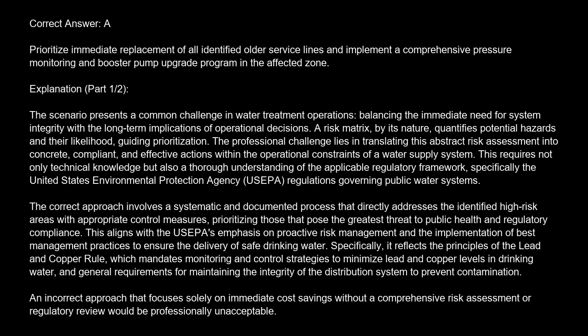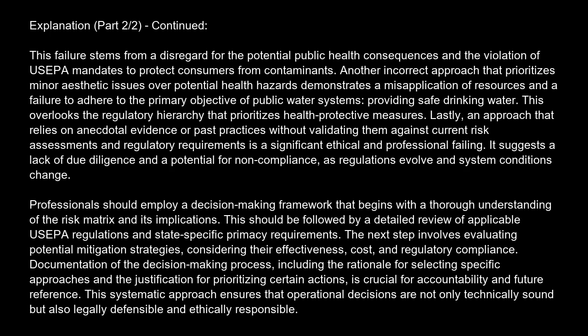Specifically, it reflects the principles of the lead and copper rule, which mandates monitoring and control strategies to minimize lead and copper levels in drinking water, and general requirements for maintaining the integrity of the distribution system to prevent contamination. An incorrect approach that focuses solely on immediate cost savings without a comprehensive risk assessment or regulatory review would be professionally unacceptable. This failure stems from a disregard for the potential public health consequences and the violation of USEPA mandates to protect consumers from contaminants.